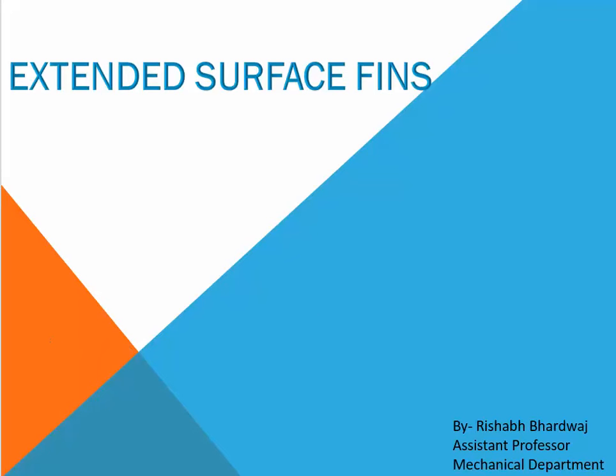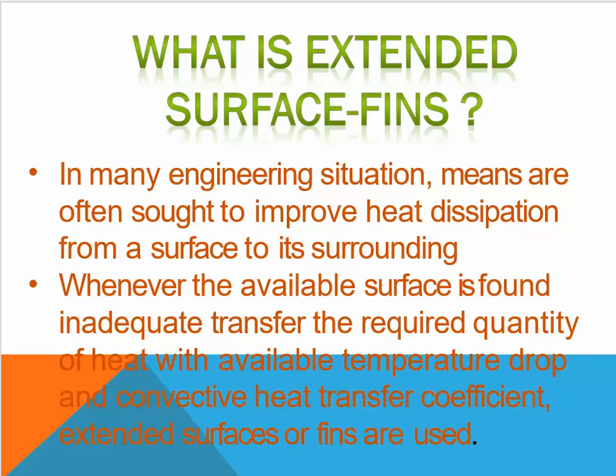Let's start with what extended surface fins are. As we know, in many engineering situations, means are often sought to improve heat dissipation from the surface to its surroundings. Whenever the available surface is found inadequate to transfer the required quantity of heat with the available temperature drop and convective heat transfer coefficient, extended surfaces or fins are used.